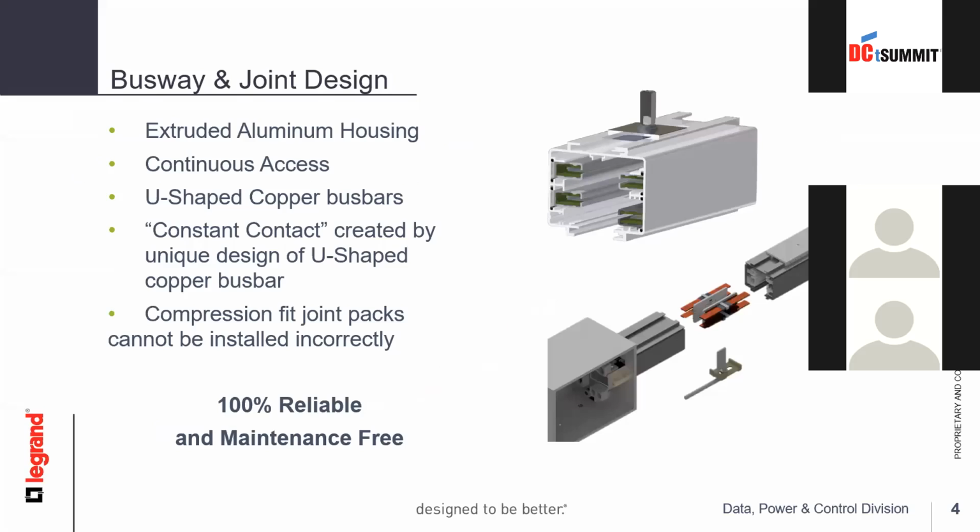The weakest point in many electrical systems is the joints, or where connectors make physical connection. The simplest way around this is to reduce the number of joints. And how do you do this? That is by making the runs of the busway as long as possible. Within Starline, we can offer up to 20 meters on a 6-meter section for some ratings, or most of the ratings actually, which reduces the joints and hence reduces the failure points.